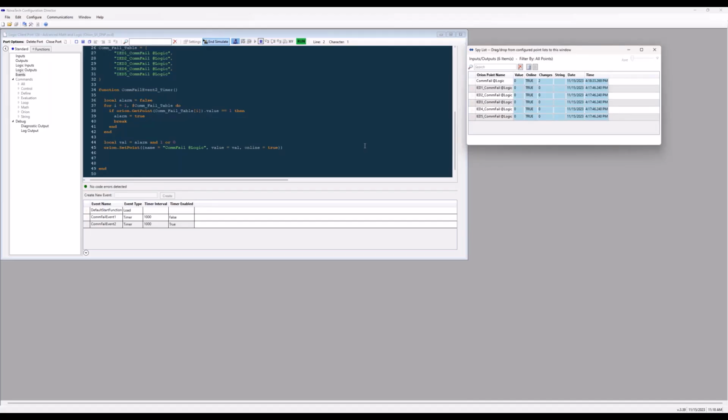This was just a demo to conclude: if you've got a small number of devices, you can use if and else. If you've got something like 30 or 50 devices, or room for expanding in the future, I would probably use code with tables and for loop. In this code, we don't touch anything in this area. We just add the number of devices and keep on expanding, so we don't have to rewrite the code again. That was the demo on COM fail.